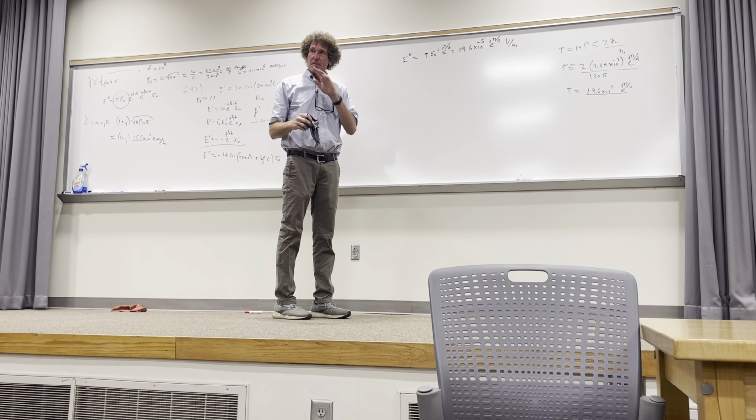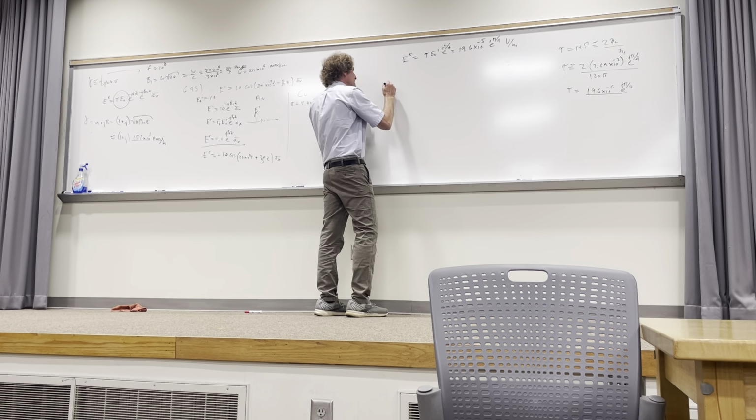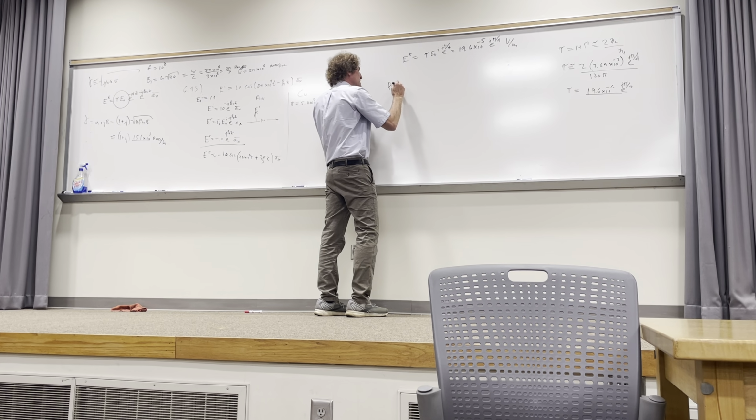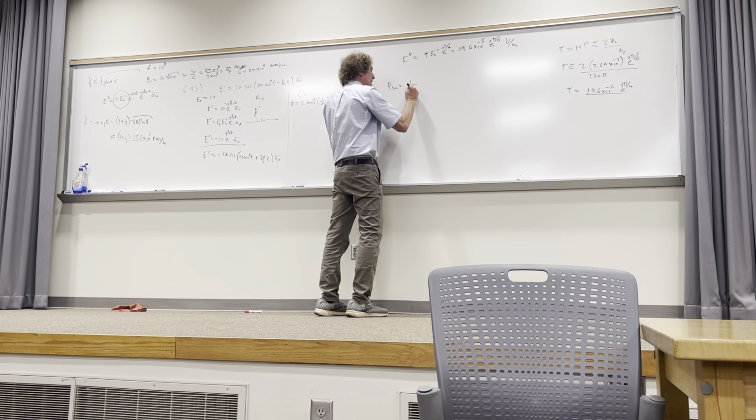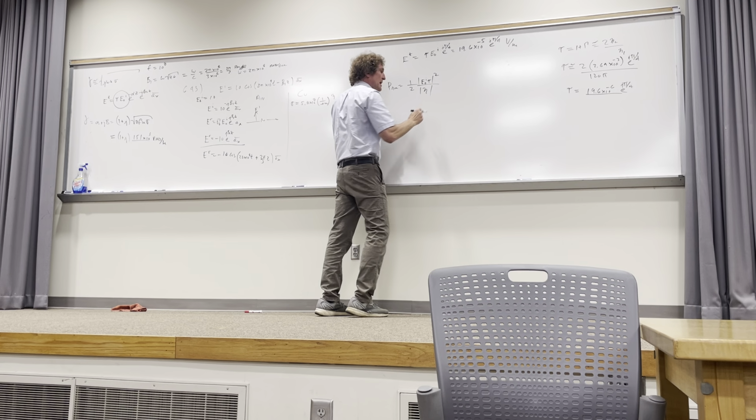Now, for the power, this is one thing you have to understand. If you have a good conductor, you have to do this. The average power, for a normally incident wave, is going to be 1/2 times the magnitude of the transmitted field, which is E naught incident times the transmission coefficient, squared, over the magnitude of eta.